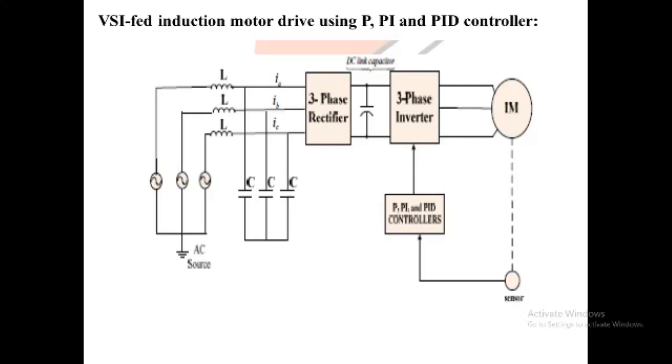In general, it can be said that a P controller cannot stabilize a higher order process. For a first order process, meaning a process with one energy storage, a large increase in gain can be tolerated. A proportional controller can stabilize only a first order unstable process.